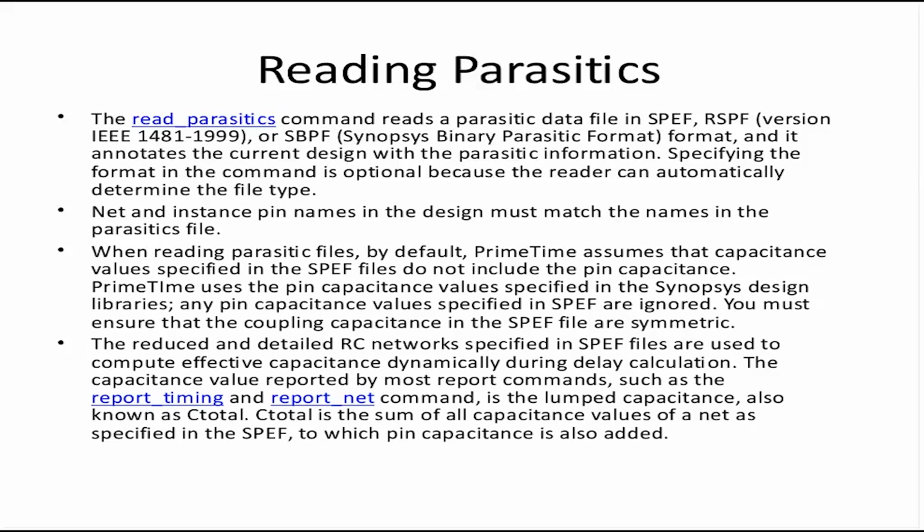In case of NLDM, I think it's the sum, but I have never verified whether for a particular net, all the capacitance inside the SPEF plus all the pin capacitance is simply the sum or not. I'm not sure, but the thing to remember is that any report you do will report a single value of cap at a particular node, and that will contain the effect of the pin cap plus the net cap.